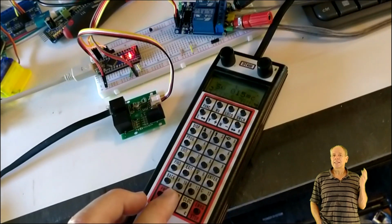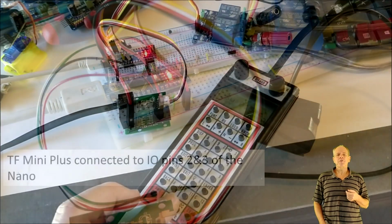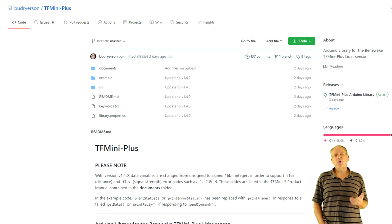Yes, it's that simple. Next, we connect and test the TF Mini Plus sensor. As before, 5 volt and ground go to the respective pins of the Arduino Nano. Transmit and receive we connect to I/O pins 3 and 2, but this is not critical. Luckily, someone has already done the hard work for us, and we can download a TF Mini library for Arduino from GitHub. The link is in the description below. Download and install the library in your Arduino IDE.